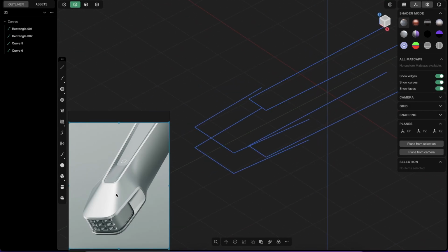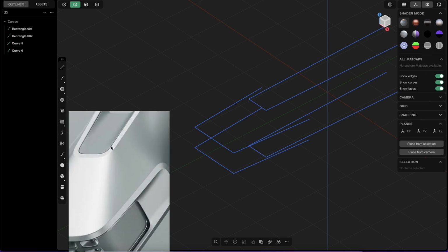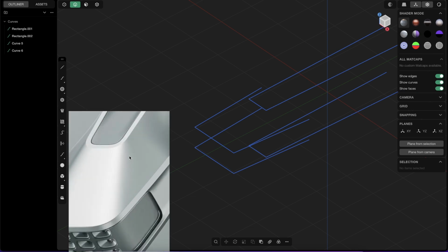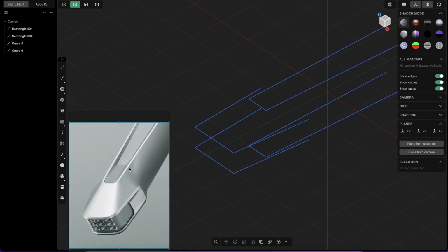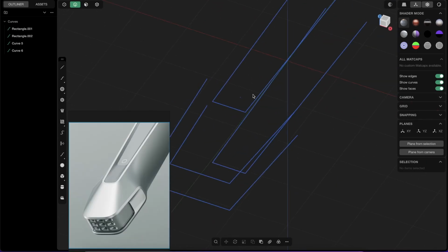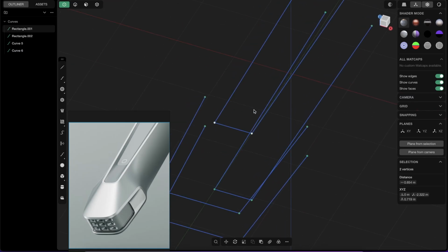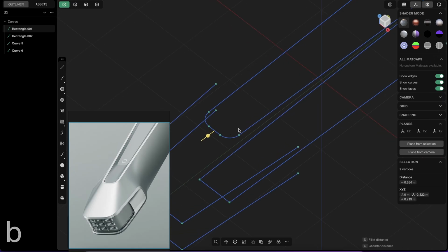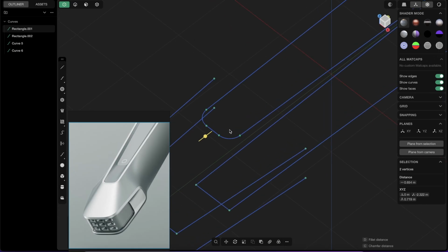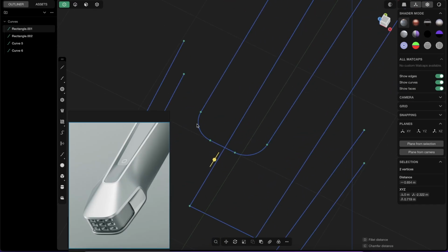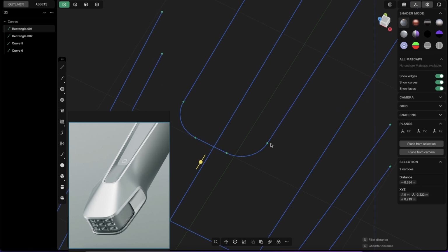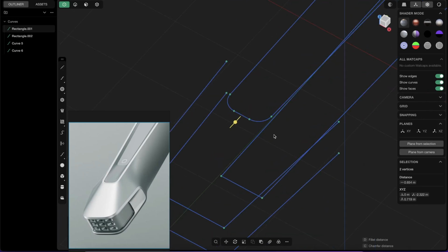And the important thing is when you have very smooth surfaces and transitions like we have in this example, you don't want to just select those points and press B for fillet and give them a fillet, because this fillet is G1. So again, not to go too deep now into G1 and G2 what this is, but basically this simple fillet has G1 continuity, so it will not be super smooth at this transition, especially when we loft it later.